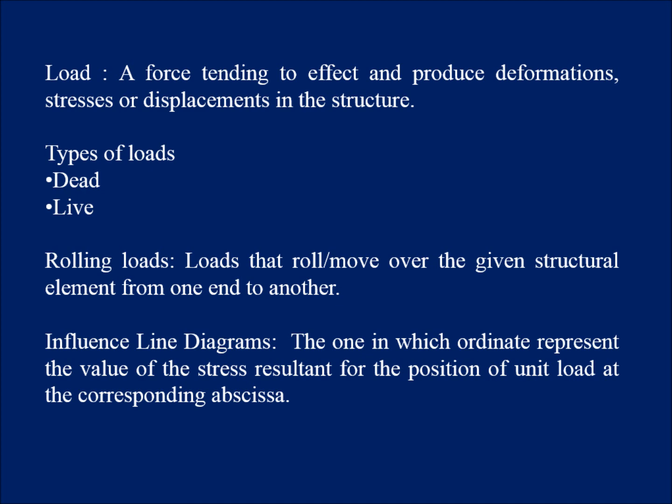Now we come on to the main topic, rolling loads. Rolling loads are the loads which roll or move over the given structural element from one end to the another. As we all know, a designer has to analyze the beams for various positions of loads so as to get maximum shear force and bending moment values due to moving loads. For this purpose, they need what we call influence line diagrams. These are abbreviated as ILD.